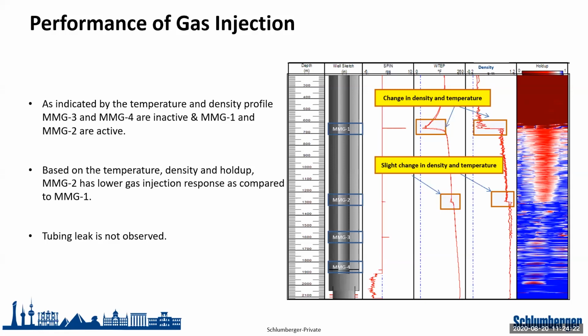So this is one application of the production tools, okay? Now this is another application for the production tool. So this is basically to determine the entry of fluids from the perforations. So this is a two-phase condition, yeah? What you see in red, these tiny squares, these are the perforation intervals, yeah? What you see in yellow is what we call calibration zones.